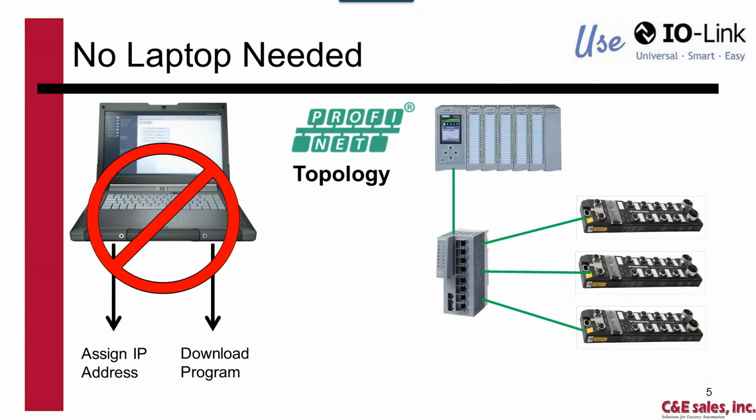Using the PROFINET topology technology, the coupler or interface module of a failed I/O station can simply be replaced without having to assign an IP address using a laptop. It is to your advantage and benefit to use these technologies to minimize downtime and to maximize profit.